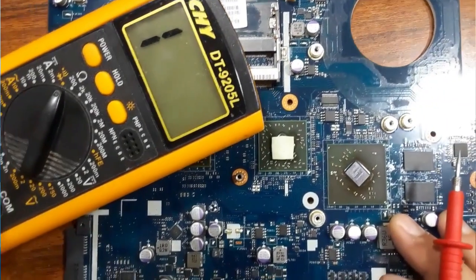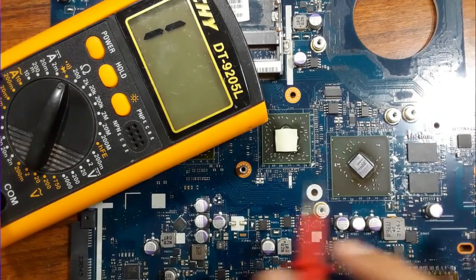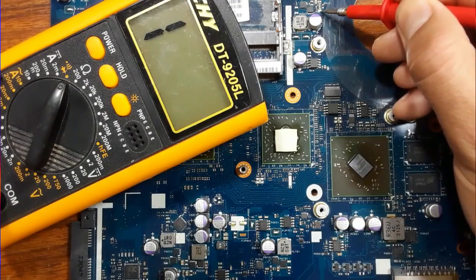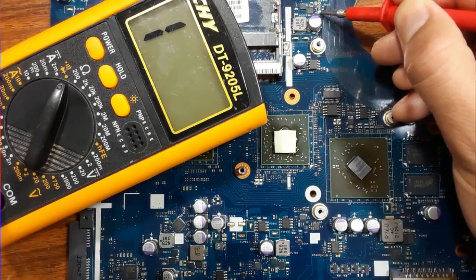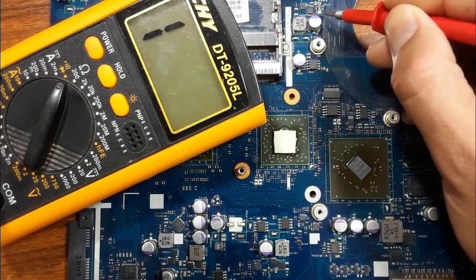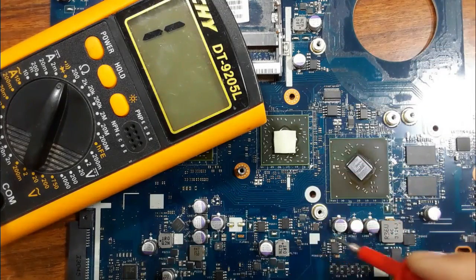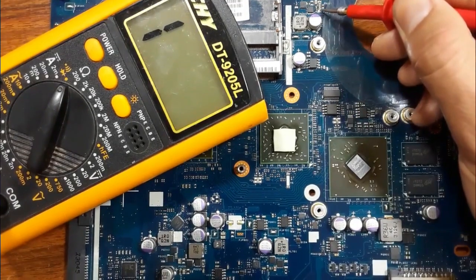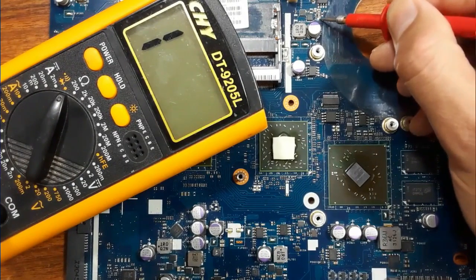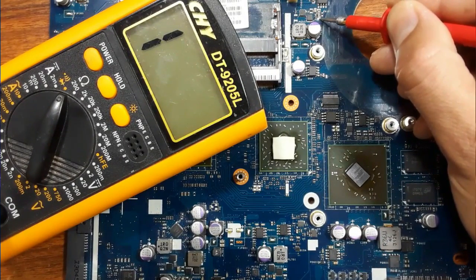So as you can see here, for example, we have many circuits. If I check between this point and these circuits, I should find a continuity. Why? Because the 20 volt should pass directly from this to all these circuits. So let's check. I will put 1 probe here in the current resistor, and then check here the MOSFETs in this circuit.